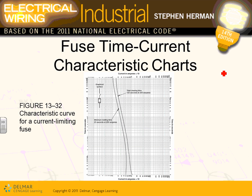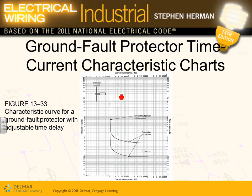If you have a fuse, it's the same thing. The fuse also has a time current characteristic curve that looks something like this, from the point it starts melting to the point it completely opens the circuit. The higher the current encountered by the circuit breaker, the faster the circuit breaker will open.